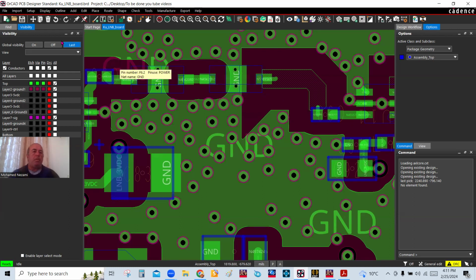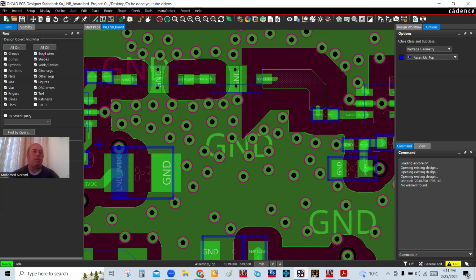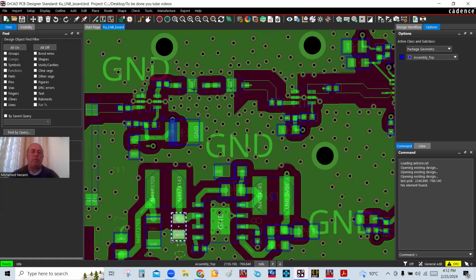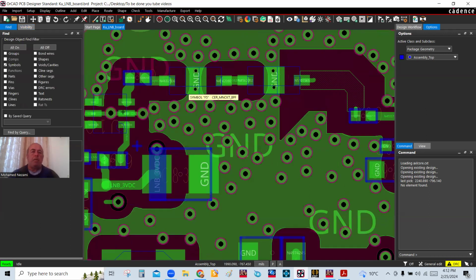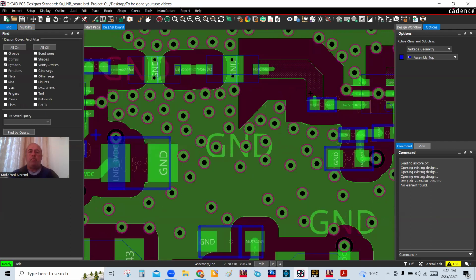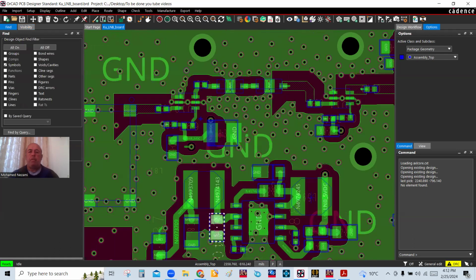This is the filters right here. So this is one filter, and this is another filter, okay? So we come in here from a previous amplification stage, and then we go into the first filter, and then we have the second one in here, and then we have some kind of microstrip line that feeds the following amplification stage.